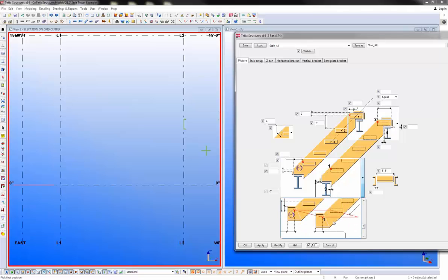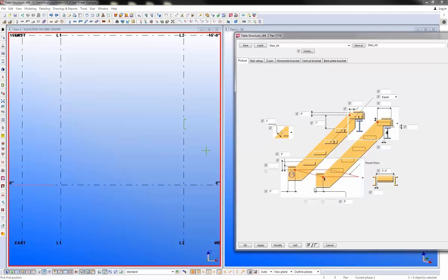So I'm going to go back to where my finished floor is going to be, my first nosing point picked. This means that I don't want a step to be created at the finished floor. I mean, that's where we're going to have concrete. And then I'm also going to set the option to frame to a beam at the top automatically. Now, you don't have to do this. You can always notch it manually.